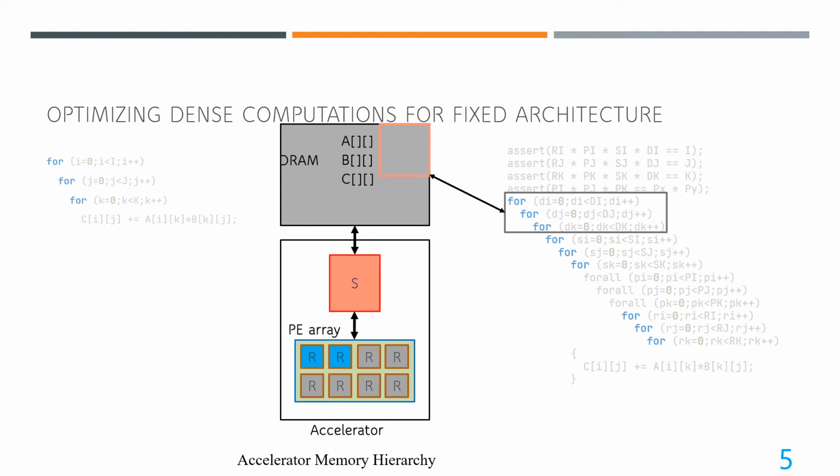At every iteration, a tile is brought into SRAM, typically a faster and smaller memory, and accessed multiple times by inner loops. We can permute these loops. Also, we can choose different values for tile sizes at various levels. Choosing different permutations and different values for tile size variables leads to significantly different performance.